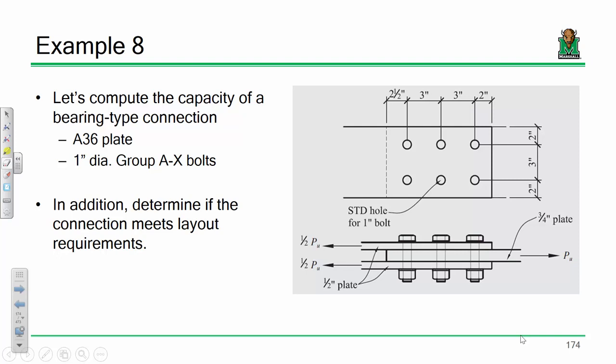As for bolt bearing, that does take a little bit longer. Remember, whenever you do a bolt bearing check, at the very worst case scenario, you're going to have 2 cases that you need to analyze. All the plates that are transmitting the load that way, and all the plates that are transmitting the load that way. Now, if you're in connection design mode and you have this ability, you can usually control your connection design where you only need to check one of them, and that'll become a little clear with the next example. But we ended up checking both of these.